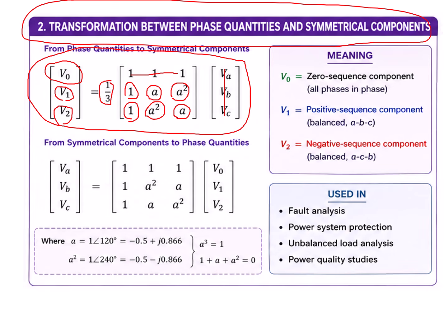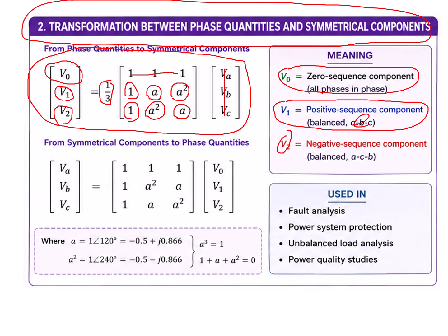So the zero sequence components are in phase and the magnitude is the same for all phases when there is an asymmetrical fault. Whereas the positive sequence will have the same phase sequence as the original signal ABC. The negative sequence has the sequence changed to ACB, because the original signal is ABC, but it is converted to ACB.